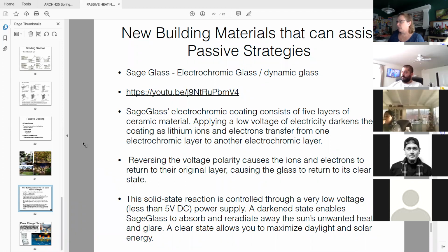It's been around at least for 20 years. Used to be really expensive. It's still not in major use yet. I don't think the cost has come down significantly, but if your design has a significant load on a west face that needs a lot of glazing and it's sending your building loads skyrocketing for cooling, investing in the glazing could dramatically cut the size of your mechanical cooling system. So it could pay for itself.